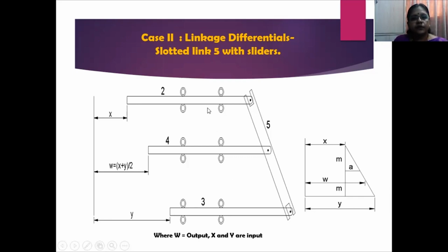And link 2 and link 3 are placed inside the slots so that they can move freely inside the slot, here and here as well. Then link 4 is again pin jointed to this link. All the links 2, 3, and 4 are made to move on guided rollers here in order to ensure the alignment in its translation motion.